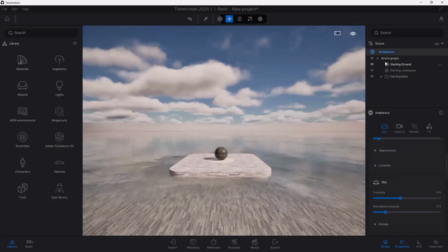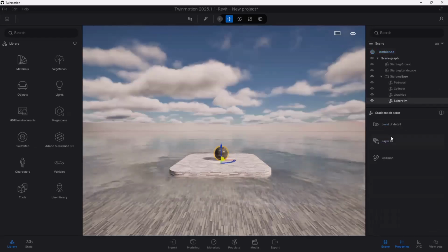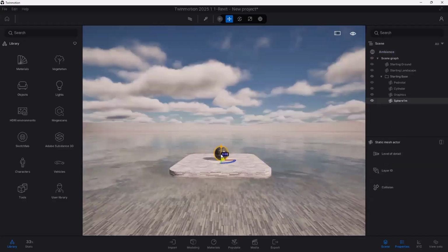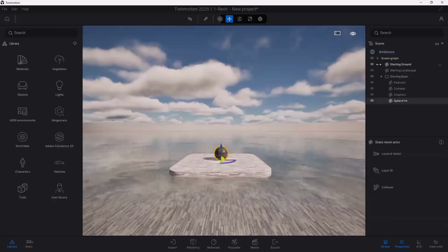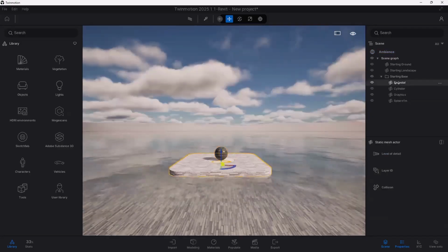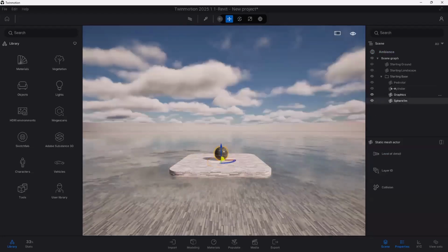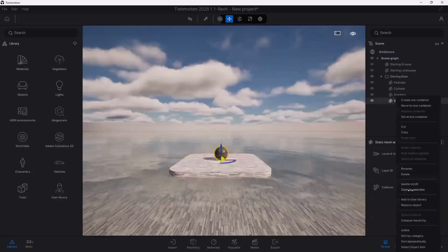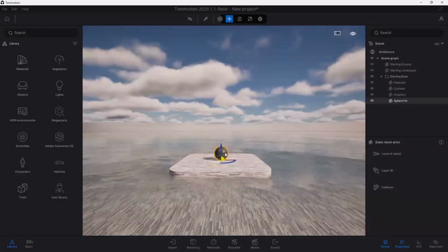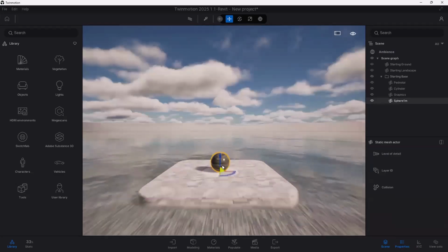But when you click on something, whether it's an object in the drawing or something on the right, you are then going to see the properties of that object. Clicking on an object leads me to what the scene is about. You'll see that within a scene there are groups, and within each group every object is listed. So this is your database, and you can click here and zoom, which is a very common way to get your zoom back. You can also click here to select something to edit. So I now have an object selected for editing, and you can see the grips.